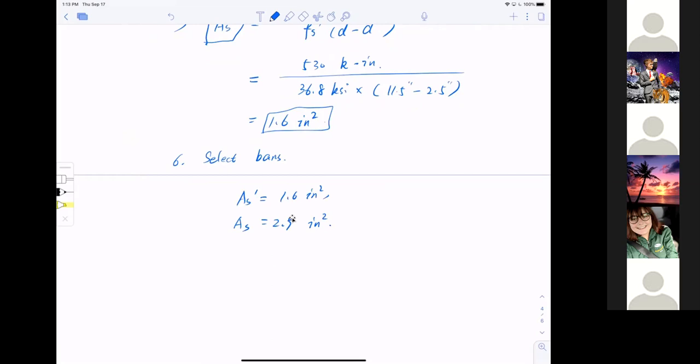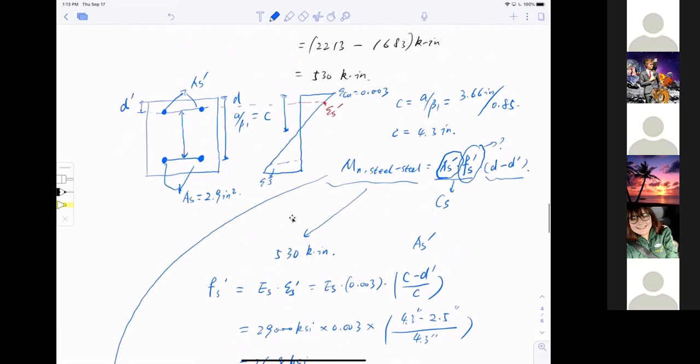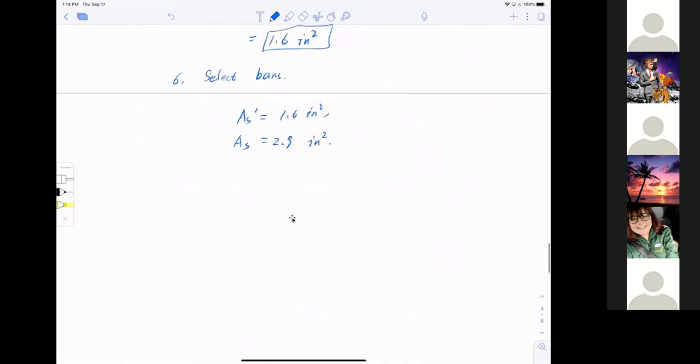Something changes. What changes? Take a look at the previous section. I put additional bars in. That means I occupy the concrete that was originally there. I'm going to say this again: I take the bars and put them in, so I replace the concrete that was there before. So I have to give it back. How do I give it back? This is how.